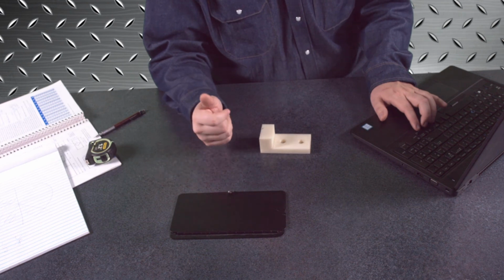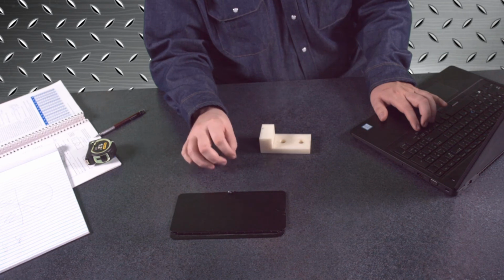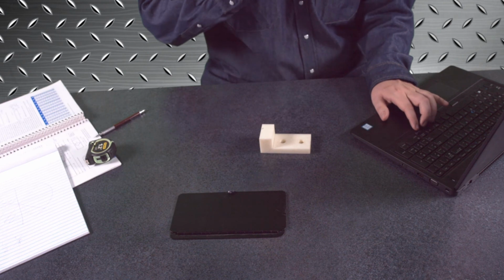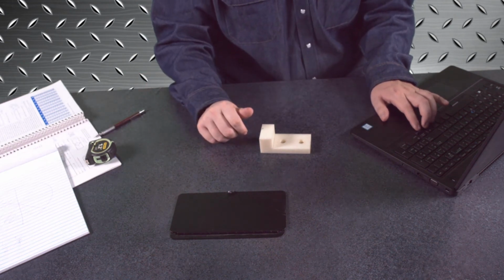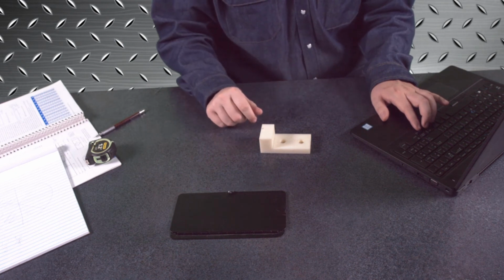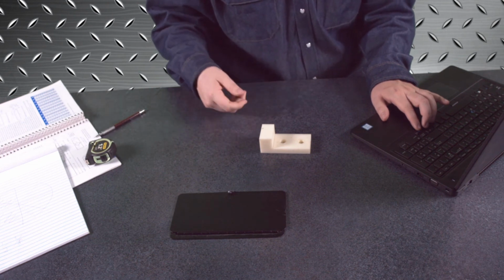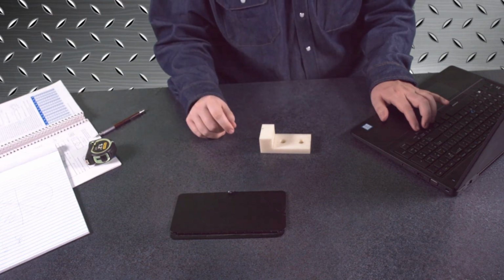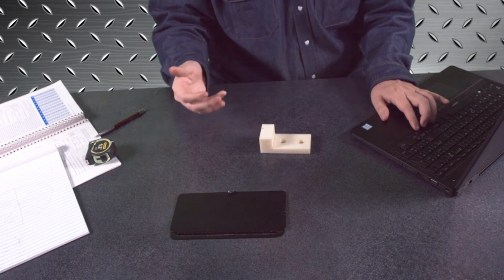If you build a bunch of different objects and you go out and measure them, that measured size will be the actual size. And then a nominal size would be if you order a 20-foot piece of bar stock and you get a little bit more than 20 feet, it's because they sell them as nominal size. It may be a 1/4 inch longer, it may be an 1/8 of an inch longer, so you don't know whenever you order several structural beams if they're all the same length. They will probably all have to be cut to the exact size that you need because they are brought to you and called a nominal size.